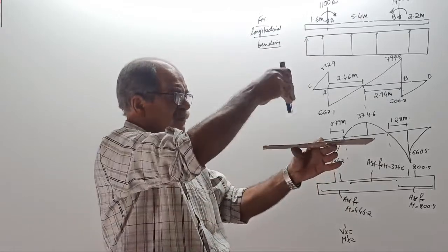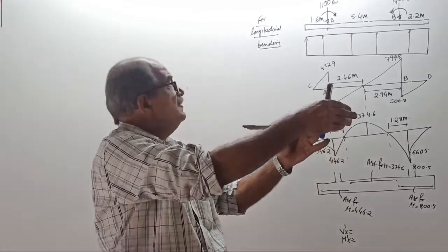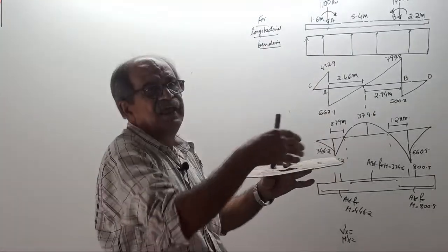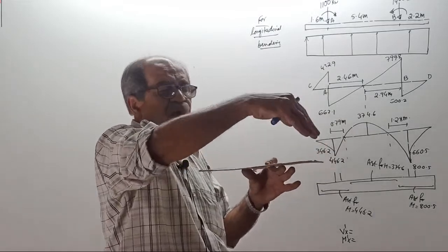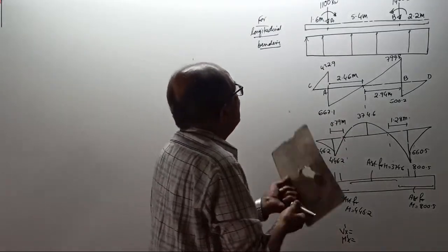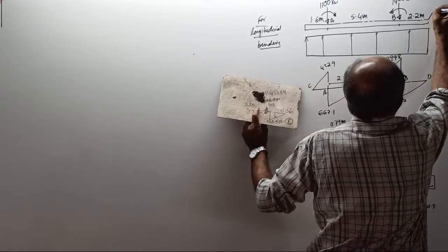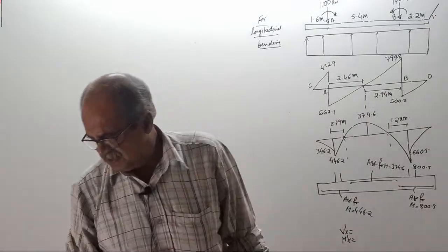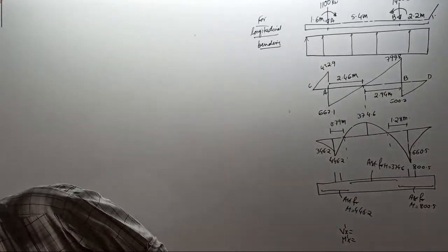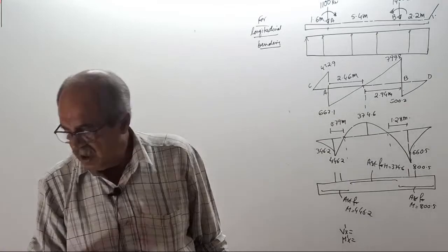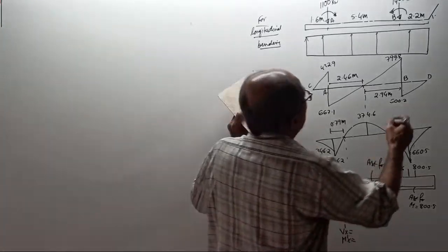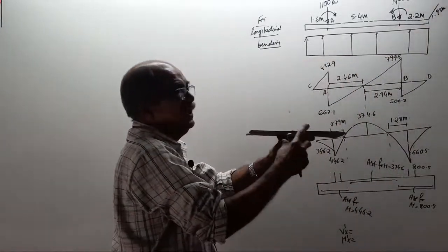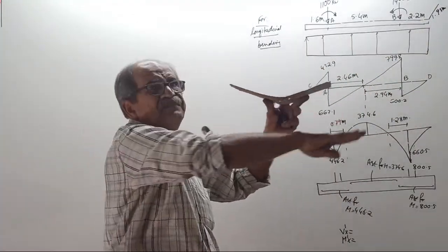See, one column here, one column here. This length, I don't know, you can calculate, some 9 point something. What is the width of footing? Tell me. 1.95 meter. Okay. Width of footing is 1.95 meter. Now see, we are considering lengthwise bending.